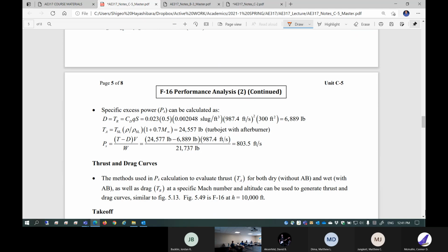So this is going to feed back to your design, and you say, okay, we chose an engine which is not powerful enough. I'm sorry, I've got to pick a bigger engine. That bigger engine requires a bigger body. Well, that means we have to recalculate the aerodynamics and make the wing bigger. That makes it heavier. Structures guys start to complain, we need to beef up the airplane, add this brace and this spar here and there. And oh, by the way, I have to mount a bigger engine here, so the engine casing is bigger. Then the aerodynamics guy says that increases the CD0. So hopefully your team is not going to get into that downward spiral internal battle. It's avoided. You have to compromise.